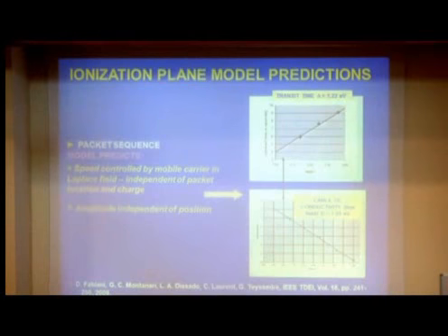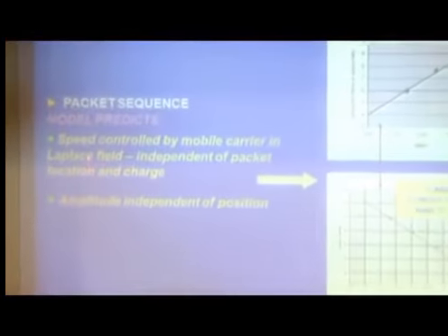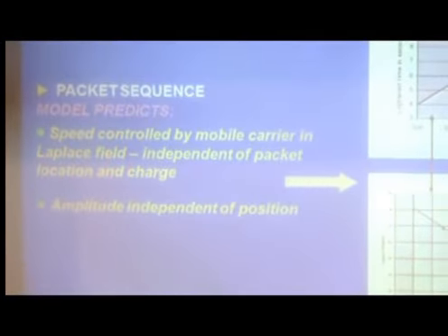In other words, the high field ionises impurity molecules, charge flows behind to one of the electrodes, the other charge is moving much slower, causes further ionisation, the charge then flows to the rear, recombines, and the ionisation front moves through the material. Under these circumstances, the speed is controlled by the mobile carrier in the average field.